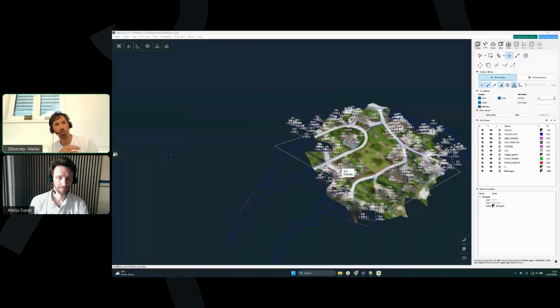If the building is fully white with no texture, or fully covered with glass, where the texture for photogrammetry is super tricky, I would advise you to fly first a bit more away from the building, at least 10 meters. Don't go to 3 meters, because at 3 meters you get a white part of the building in the picture, and in some cases the picture will be fully white. Also reflections from windows, all this stuff is super hard for the software, but with the right mapping you can solve this easily.